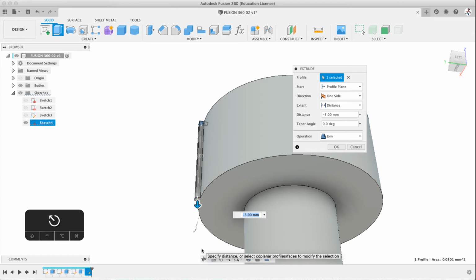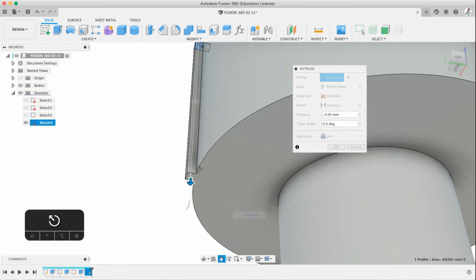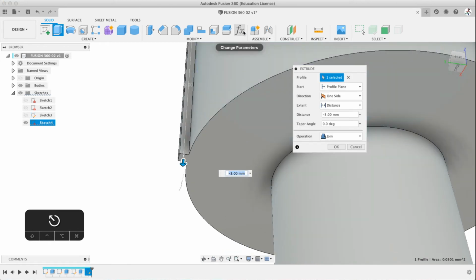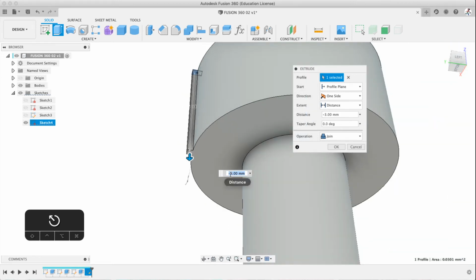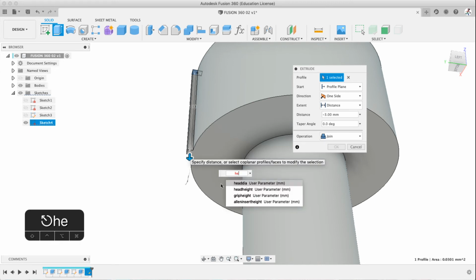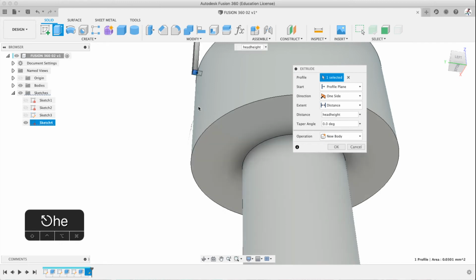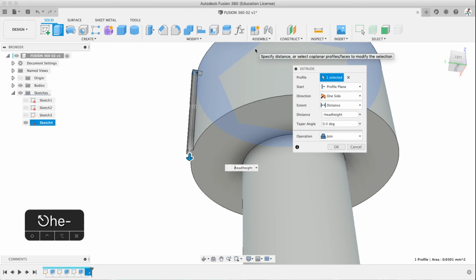But here's the problem, and here's where it gets complicated. And this is why explaining things is really important. Like I mentioned, my friend just told me yesterday. The parameter is the head height. If I set this as -3, which is that distance, then when I change that parameter, it won't change this, but it will change the head height. It'll have this weird overhang. We don't want that. So I need to make it the same just for parameter's sake. But just as an idea, just remember that you can just click for distances to bring stuff out. That's the second, maybe 10th quick tip so far.